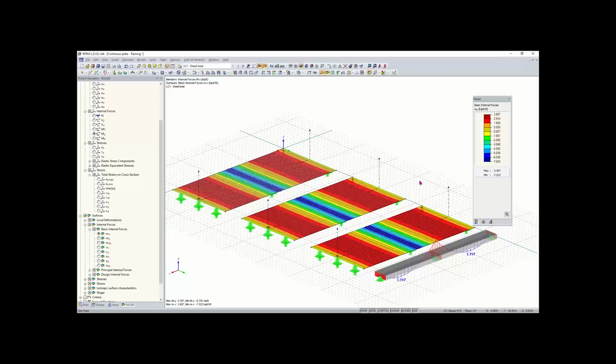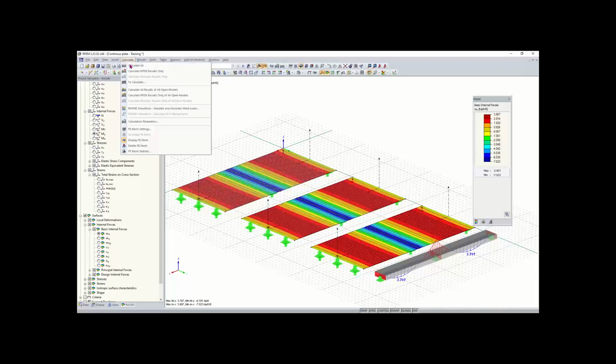I think exactly as Alex had mentioned, it's basically a test and trial type process where you continue to decrease the FE mesh. And exactly as he says, if your results are changing significantly, then you know your FE mesh is not refined enough.